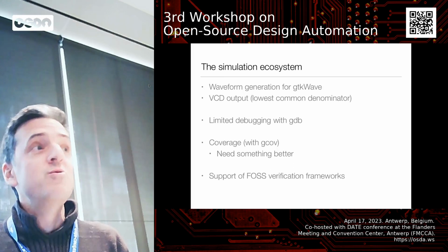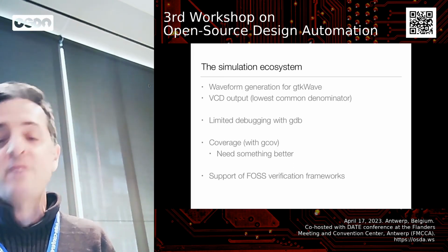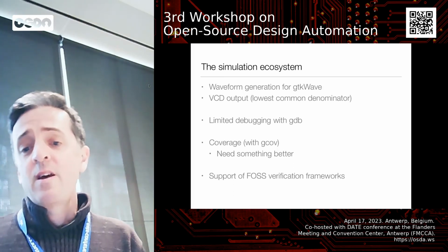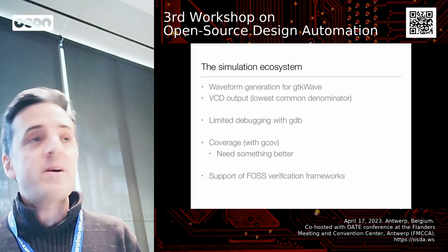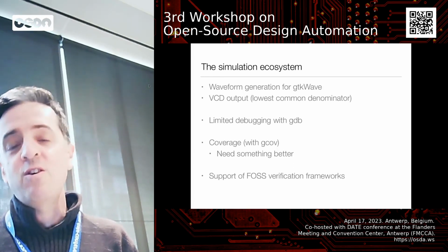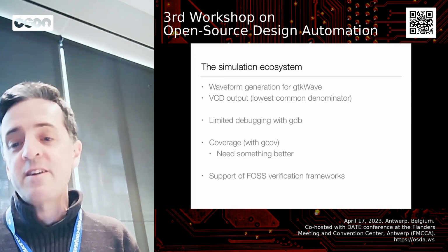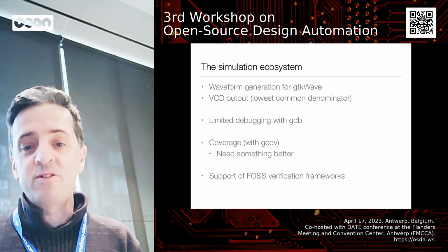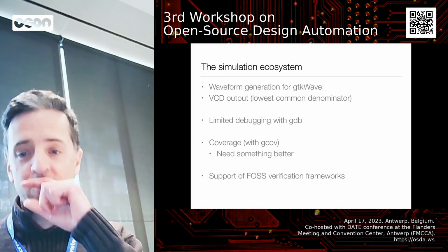In order to debug your circuit, you can use GTKWave, which is also a famous waveform GUI. To do that, you can either generate a VCD output, which is slow and large, or we can also generate a specific format designed for GHDL and GTKWave, named the .ghw file format, which is a little bit more compact and more powerful.